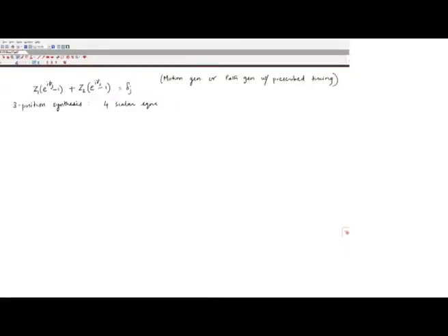How many unknowns? We will have 6 unknowns. The unknowns are Z1, Z2, 4 unknowns there, and depending on if it is motion generation, the unknowns would be phi 2, phi 3, or for path generation with prescribed timing, the unknowns are going to be gamma 2, gamma 3. So, you will have 6 unknowns, and therefore, you have 2 free choices for the 3 position problem. We have seen this before. The 2 free choices, we could either pick the 2 angles, make this a system of linear equations and solve for the vectors Z1 and Z2, or we could pick one of the vectors Z1 and Z2.